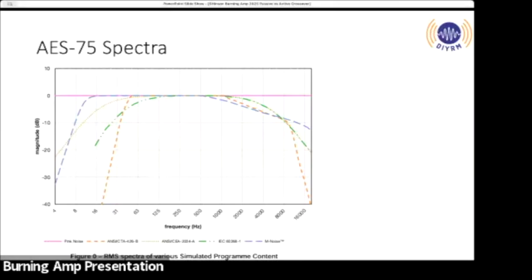Remember that chart I showed where that little bit of area in the dB scale for the Linkwitz-Riley, right? Well, think about how much area this is. That was over half an octave at the corner frequency of the crossover. This is starting at 500 hertz, so 1,000 hertz 1 octave, 2,000, 4,000, 5 octaves of dropping power in that spectra for music.